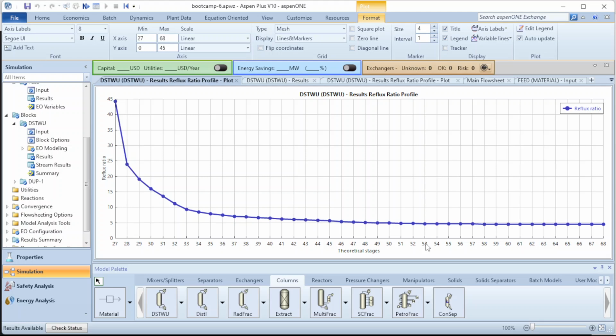The operational cost will also be low, since there will not be more energy needed to do cooling and heating. But the cost for installing the stages will be higher. If the stages are trays, the cost to install the trays in the distillation column will be higher. If it's a packing, the cost to pack the column will be higher.